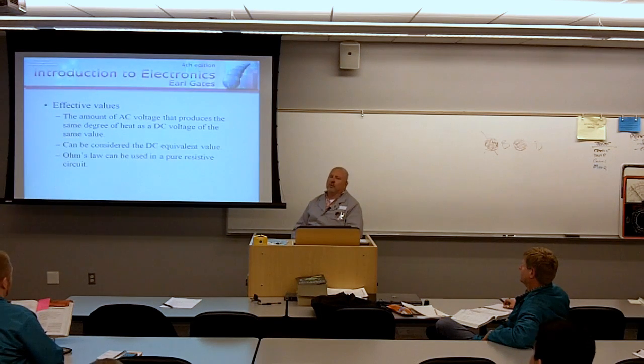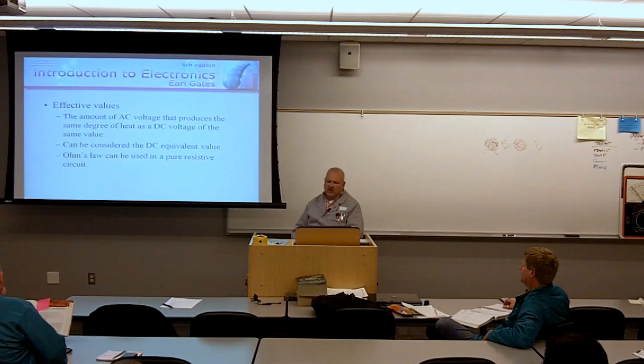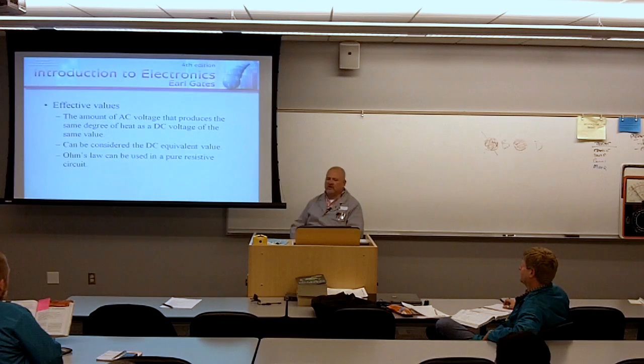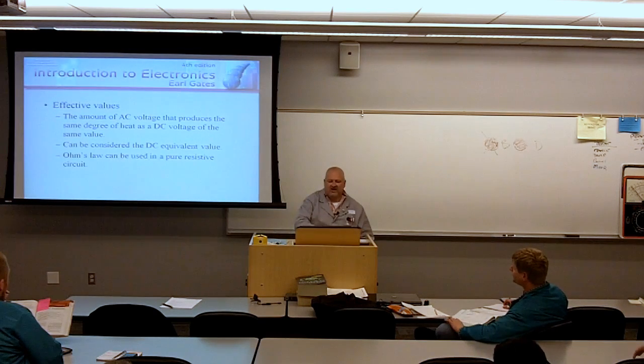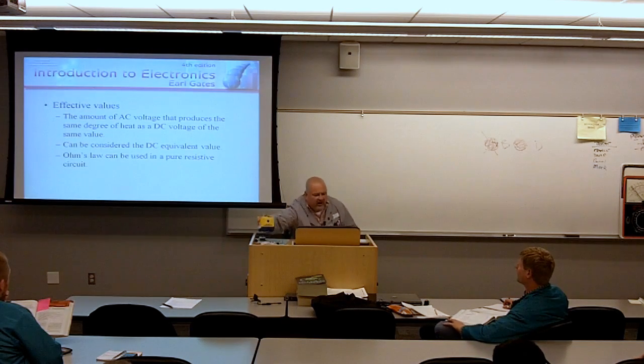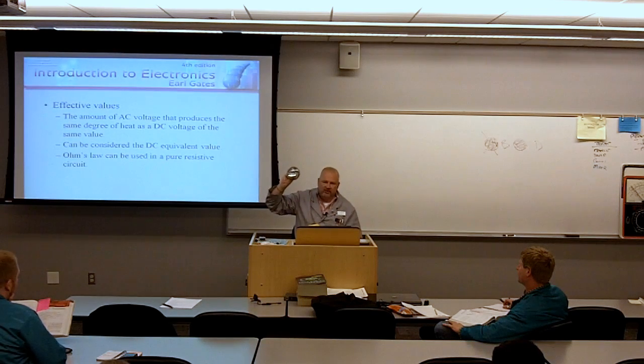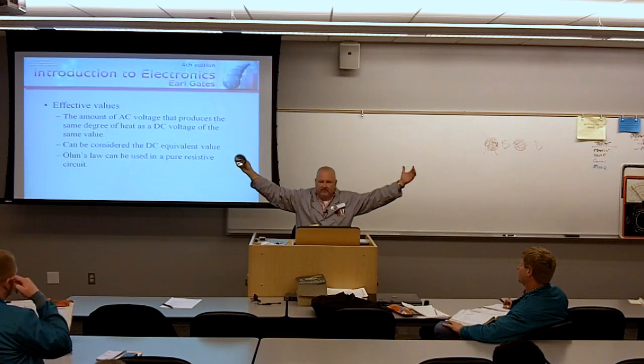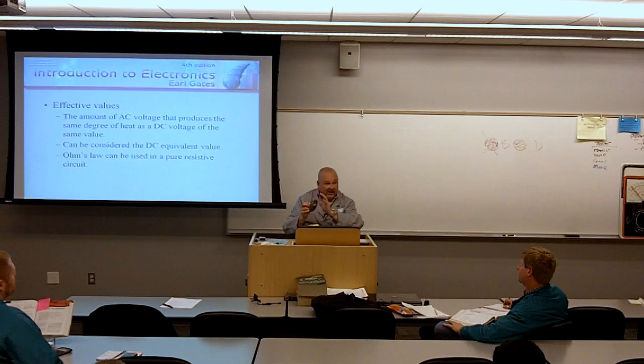One of the things that I'm going to want you to do when you're dealing with these types of circuits, AC resistive circuits, is use the effective values. The effective values are the amount of AC voltage that produces the same degree of heat as a DC voltage of the same value. Remember this? When I apply 13 volts to this, it's going to be this bright and this hot.